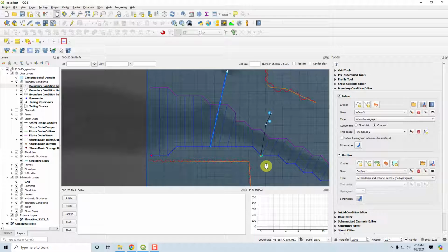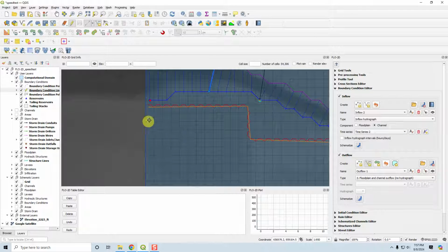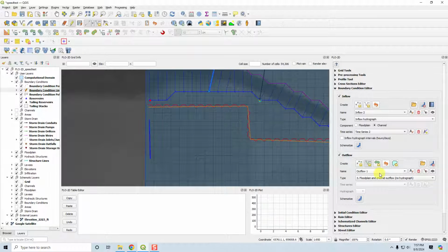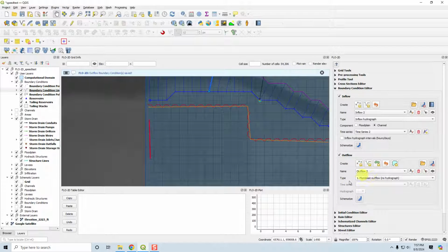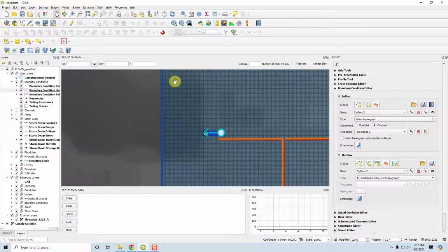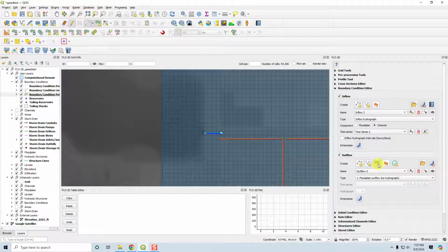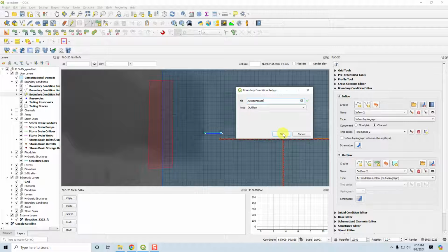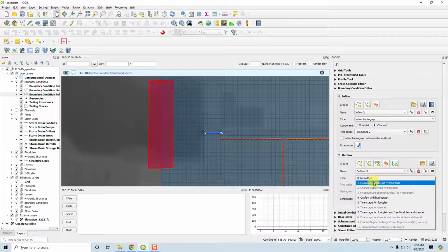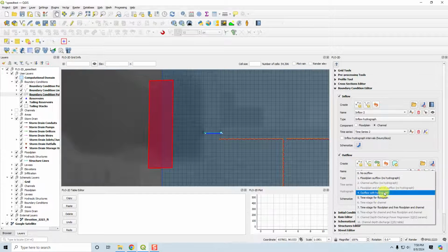And then if I wanted to do a polyline, that would be maybe like this, and then I'll right click out that outflow, and then I'll click the button again, and then you can do floodplain with no hydrograph. Or if I had a whole area and I wanted the plugin to define the outflow condition, I could use this tool, right click that, click OK, click Save, and then set that to floodplain no outflow, or you can set that to a multiple domain exchange, or a time stage, with a floodplain.